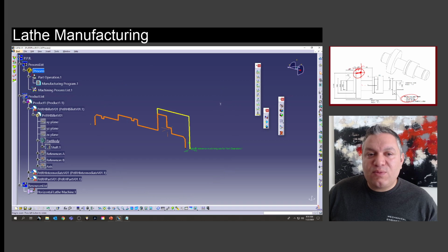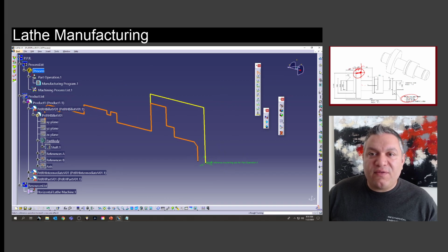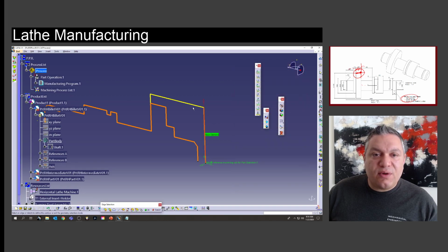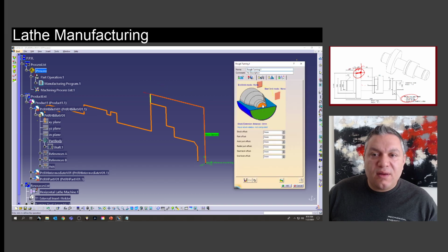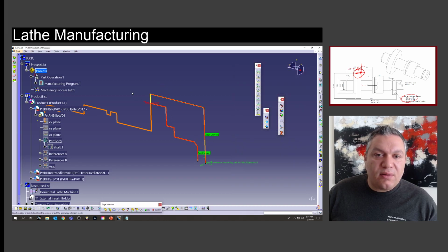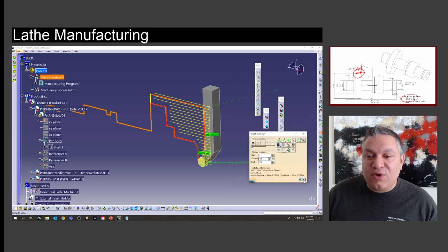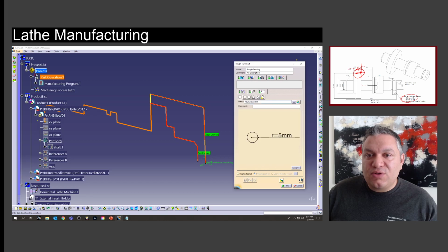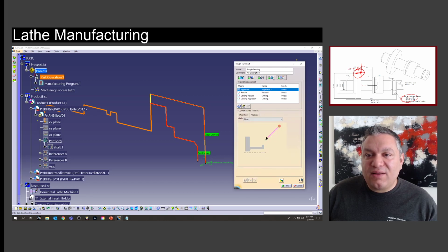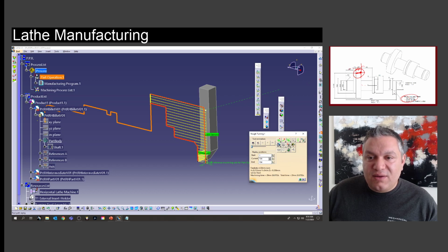Well, we will know very shortly, because all we have to do is a roughing operation here. So let's start with the roughing operation. We're going to select the billet and we're going to select the part. We can set the end limit, or change it to ask it to do more, and how much offset you want it to have. I'll go ahead and press these buttons. Okay, this is definitely not a roughing tool, so make sure you select the right roughing tools, but this is definitely not your roughing tool.